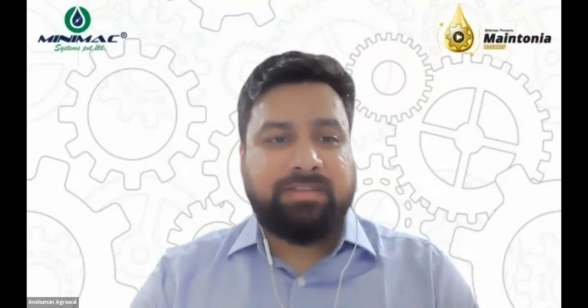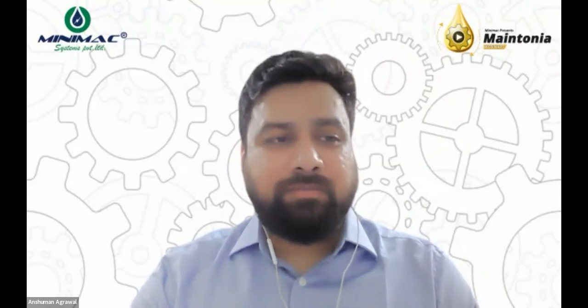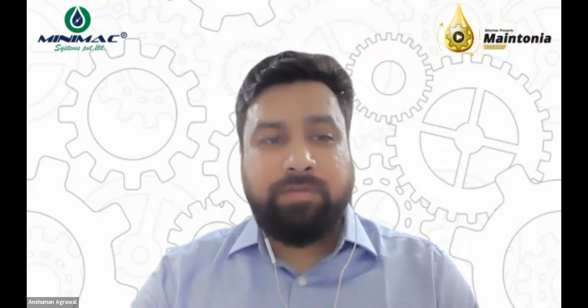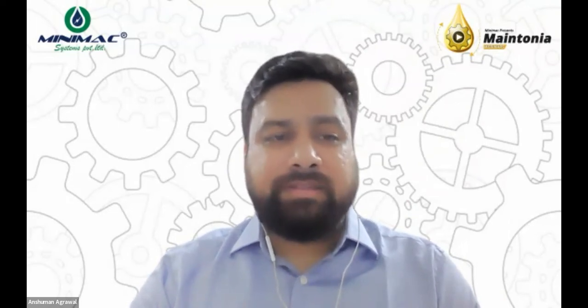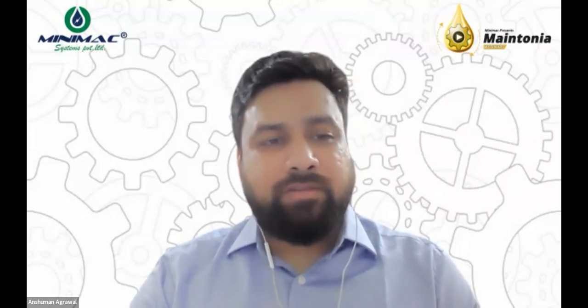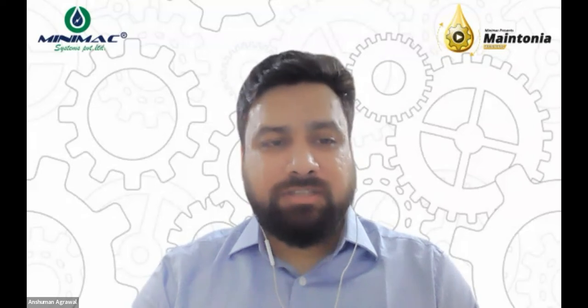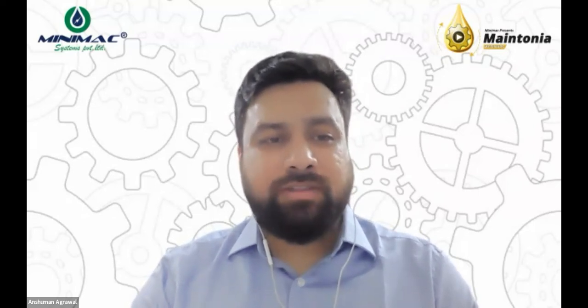The next question is, will the use of desiccant breathers work well in managing moisture in FRF? Yes, to an extent, that these desiccant breathers have that desiccant content in them. Many times we do adopt these breathers, but we don't maintain them regularly. We don't replenish them or regenerate them. And what happens as a result? They are not performing the task they are meant to. So it's very important to have certain accessories to perform, but at the same time, we need to check what they are doing exactly.